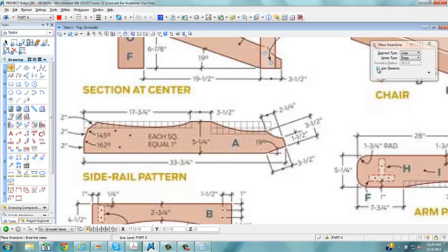Now make sure that when you do this, we don't need to, we'll join elements later as a shape because we need to do something up here on this little curved portion. So I'm going to start right up here on the top, right there. We know that that line is 2 inches long, so I'm going to hit the space bar to go into distance angle. 2 inches by 145 is the degrees. Whoops, it goes the opposite way, so I need to type in negative 145